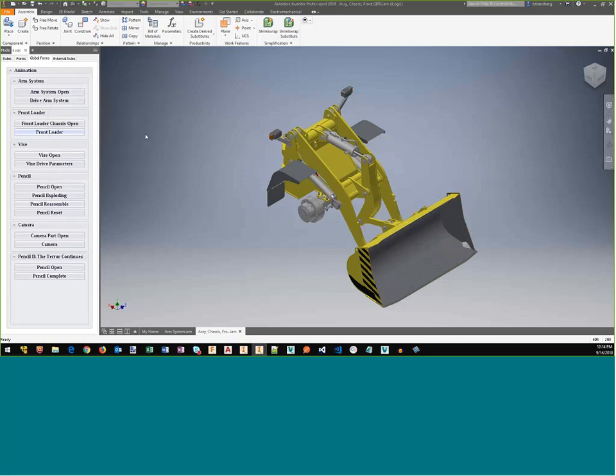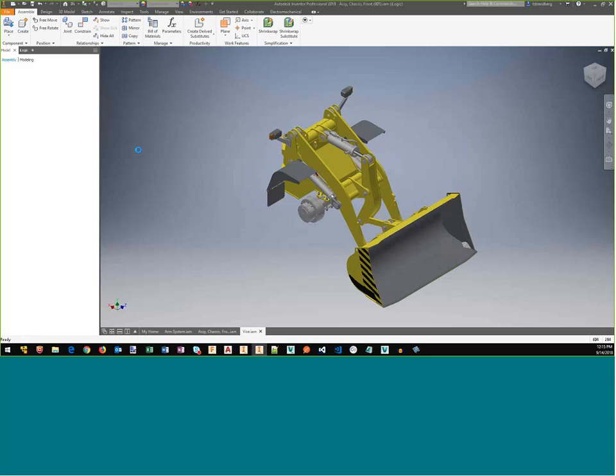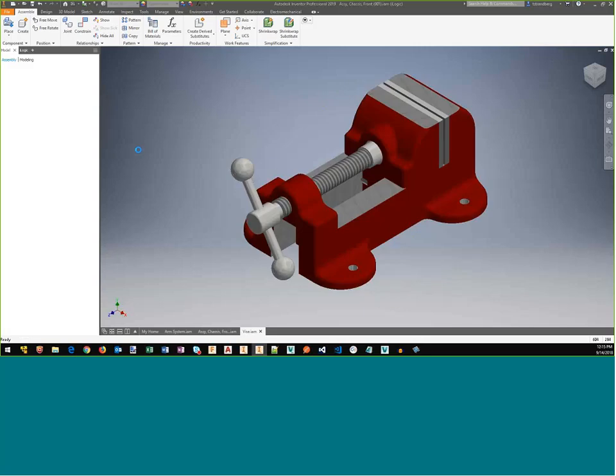So we're just driving those parameters through a range. Very much like how some of you may have driven constraints before. You know how you can right-click on the constraint, tell it to drive that constraint, and it just actuates on one constraint. Well, here, since we've got programmatic access to those parameters, we can loop through, sometimes at the same time, multiple parameters.